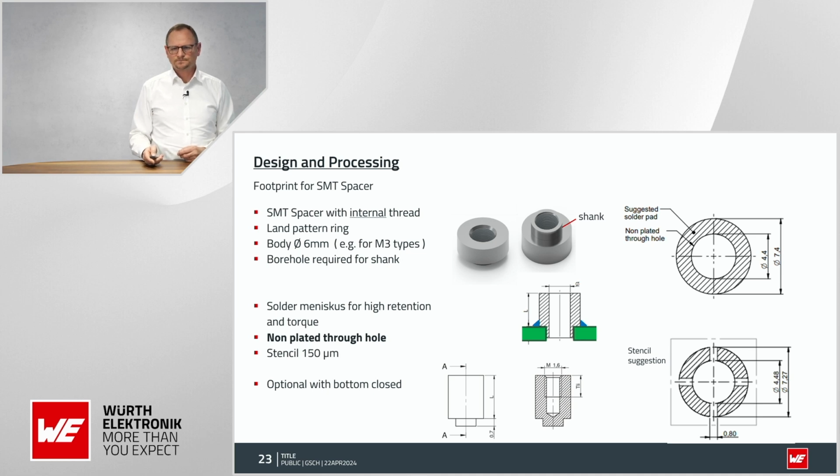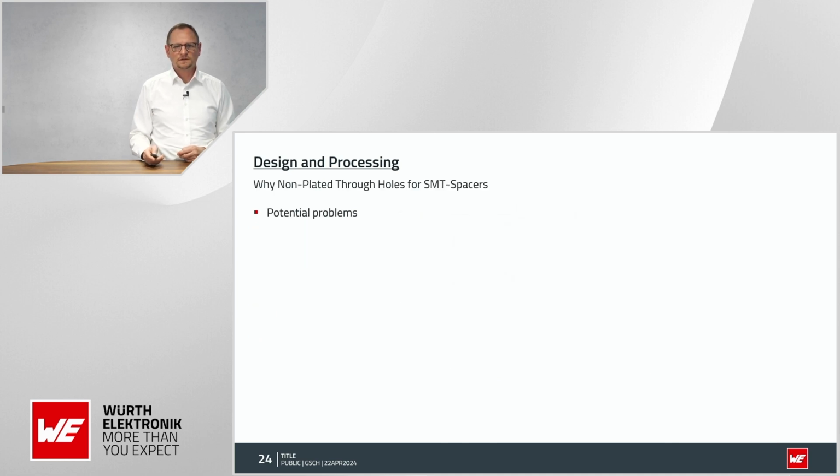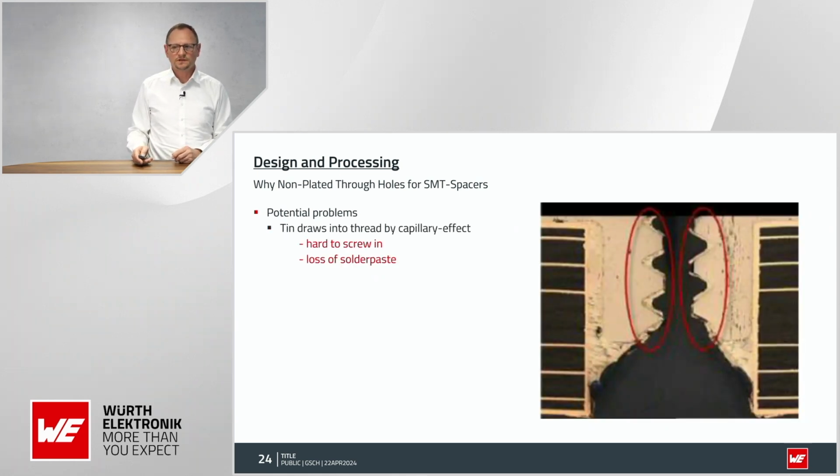And coming to the next thing: why do I insist that we use a non-plated through hole for the SMT spacers? There could occur potential problems. One of the problems you see here, and that's a real cut-through model. We can see that this is the solder area. This is the area of the component itself.